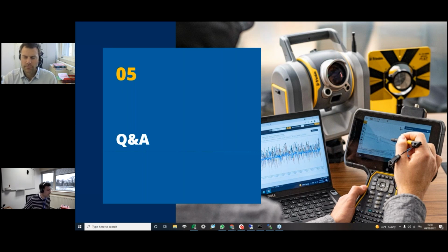Do you have any availability to measure vertical displacement with the accelerometer during the event? Good question for Bart. If we integrate, probably. I'm not sure. Not at the moment, no. We would rather calculate third octave analysis, for example, directly on the background mode, vibration dose values, RMS values, and this kind of calculation, but not really the displacement at the moment. Okay. Very interesting. Thank you.